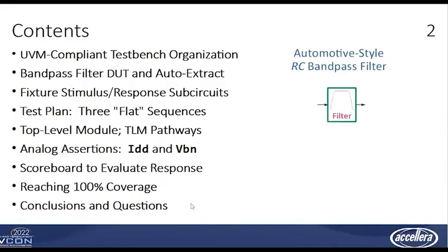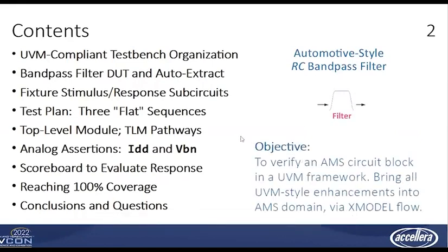We're going to be looking at a UVM compliant test bench written from scratch to verify the features of an automotive style bandpass filter. Our objective is simple. We want to bring in all the familiar UVM enhancements into the AMS domain. Modular components, TLM connections between components, UVM sequencing and phasing, and configurable test length and other knobs. We'll rely on XModel from Scientific Analog. XModel is a plug-in extension to logic simulators like VCS. It'll handle the analog content.